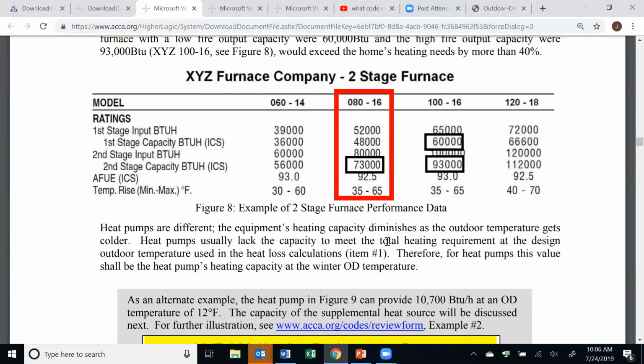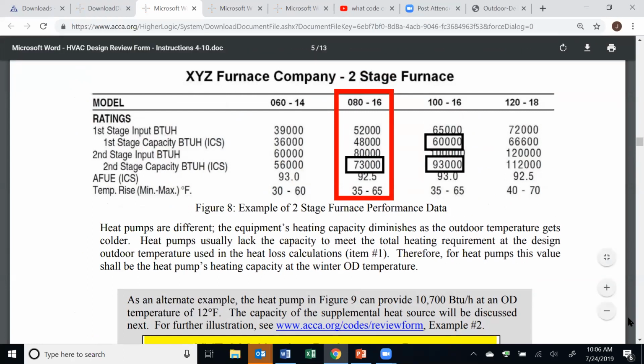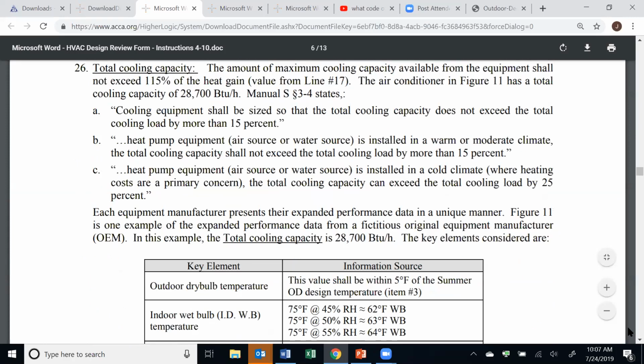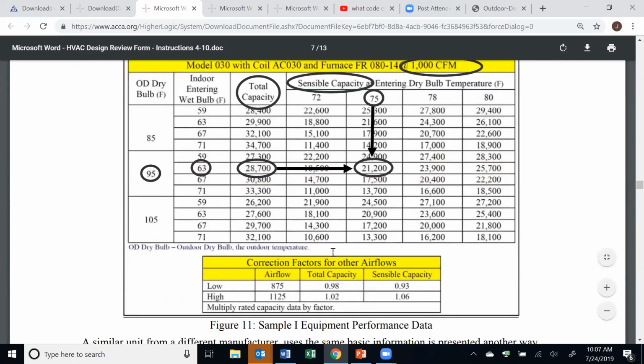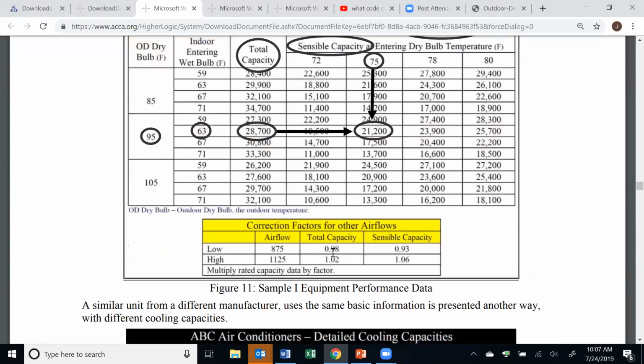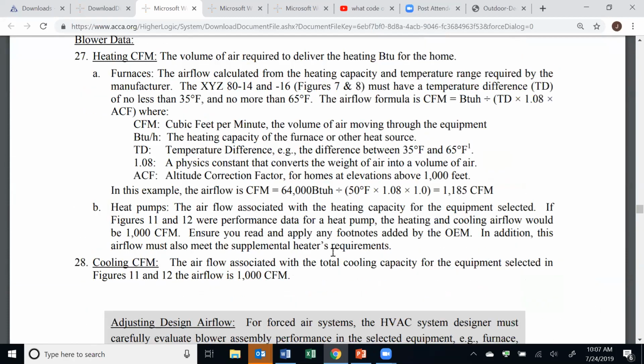And there's typically a limit switch. They call it a high limit switch. So if you exceed that 65 degree temperature difference, and for the sake of argument, let's assume we've got 70 degree air, because that's simple math, 70 coming in plus 65 degrees of heat added, then we should see no more than 135 coming out of the supply plenum. And if it does exceed that, the manufacturer puts in a switch and says, hey, we're going to shut this furnace down, let it cool off, and then we'll try this again.